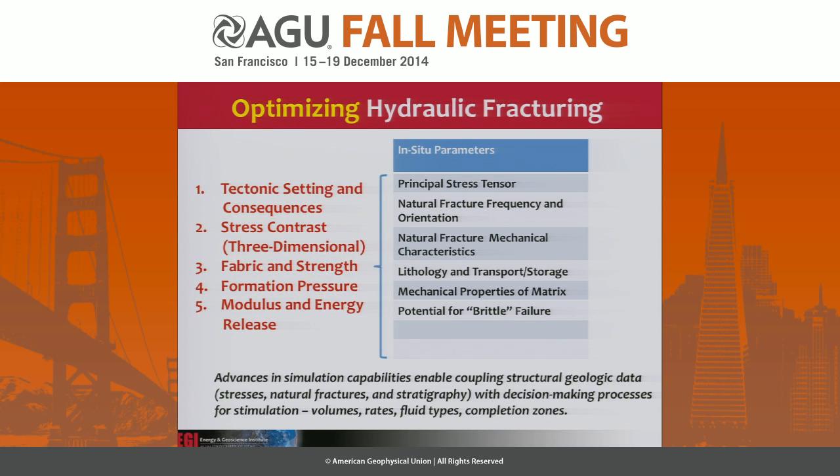And then finally, we take these controllable properties and these intuitive in-situ properties or mechanical properties, and we can ultimately relate these to specific geologic controls. And that's one of the goals of work that I'm currently involved with in terms of looking at different geologic environments, trying to infer characteristic signatures for hydraulic fractures, both during large volume treatments and during small treatments that are designed to infer properties of the reservoirs. We commonly call those diagnostic fracture injection tests. So in terms of these, let's look at them.